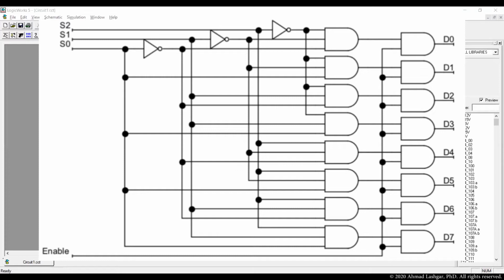In this video, we are going to make a 3 to 8 decoder with enable control. This is used in register file for enabling write signal of one specific register. We have total of 8 registers in our mini processor, so that's why we use 3 to 8 decoder.